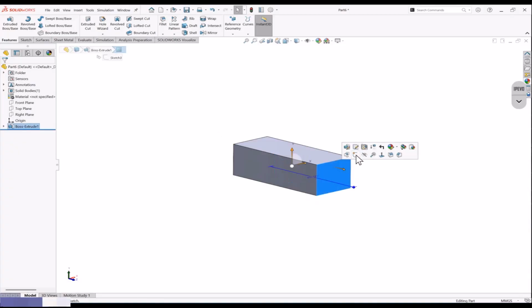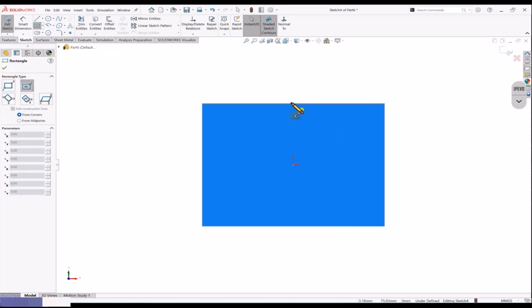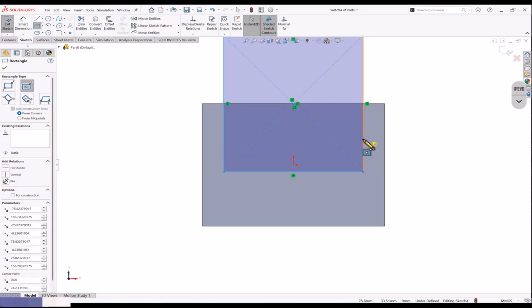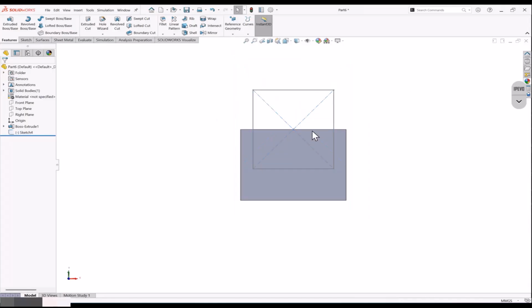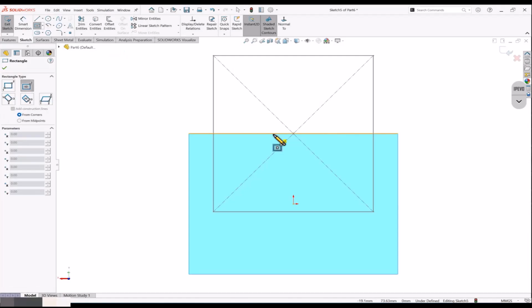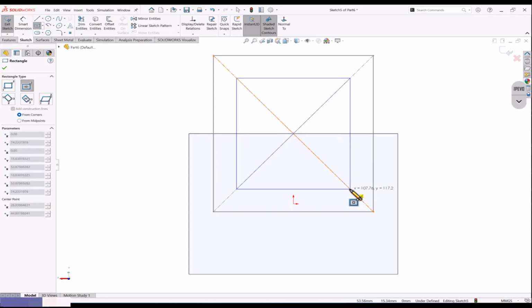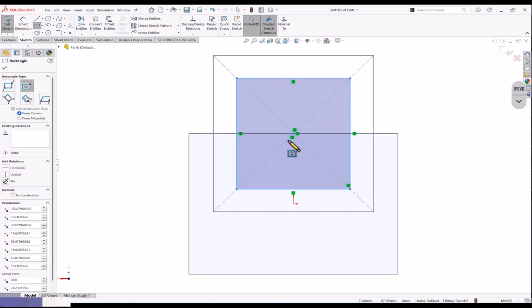Now let's start to cut this. We'll select this face. So how you want to cut the part, define the cross section. Okay, let's make a bigger cross section this side. This portion I want to cut from the part, this much area. Exit. And I'll go to this side and I want to cut a little left, okay, less depth, less width of the part, and exit.